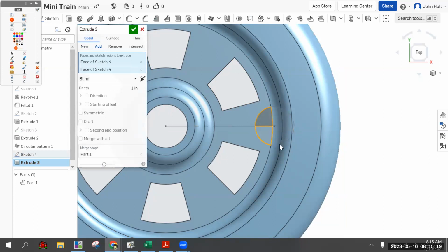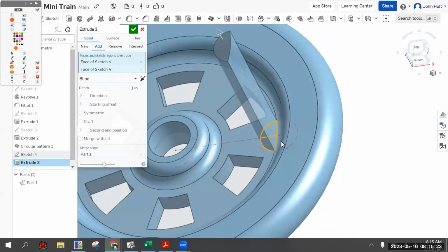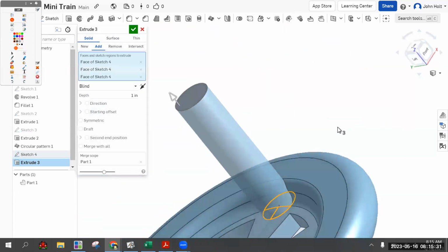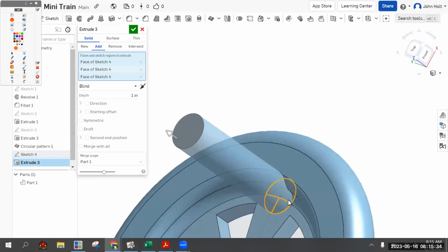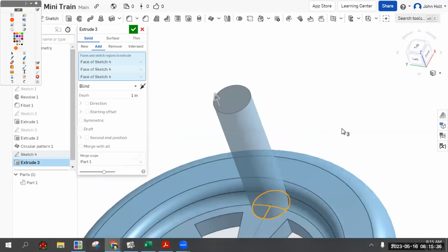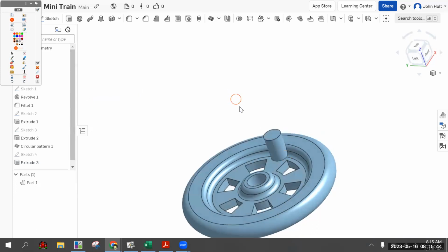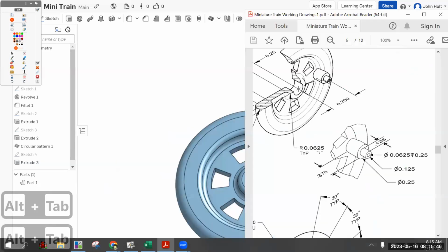Is it not letting me do? Are you kidding me? There we go. Somewhere where you get everything. Okay, so somewhere where you get everything, I had to find that extra spot there. And the distance of this first extrusion is 0.375. And finish the sketch. Then only 2 more moves.